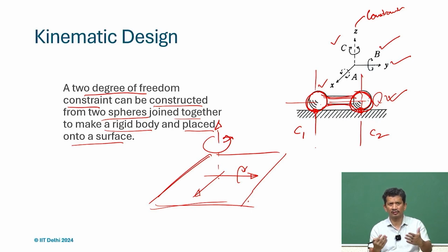So, there are no constraints. So, it is not a valid choice. Or if we press, it means it is infinitely rigid. So, it will stop the motion and then there will be no translation along z axis. So, there will be constraints. So, along z it cannot move.